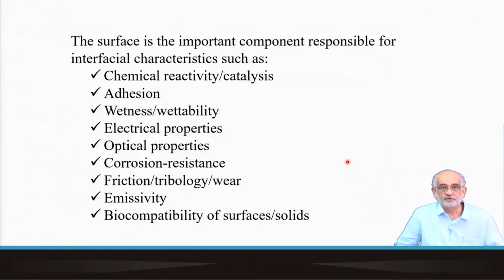The one very important part that I would like to convey here is that I told you that surface energy or reactivity arises because of the difference in structure and atomic bonding situation at the surface compared to the core or the bulk. And surface engineering or the surface related properties arise primarily because the surface has usually the highest concentration of stresses, and also compositionally and structurally they are different than the bulk.